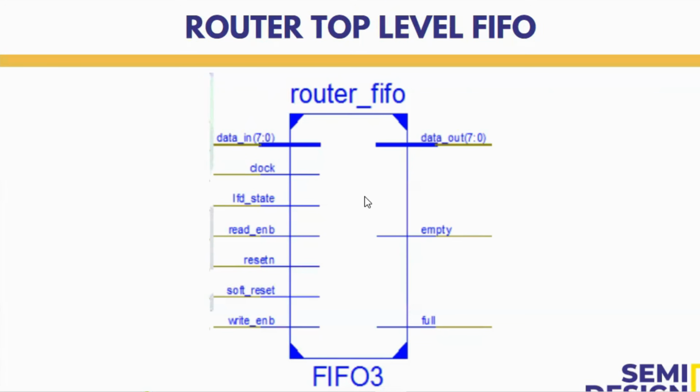I'm not sure exactly how many seconds. And if it is timing out, if that valid data present in the FIFO is not read, then it will time out and initiate a soft reset to accommodate the upcoming data, because it cannot wait too long, right? So in that case, it will initiate a soft reset.